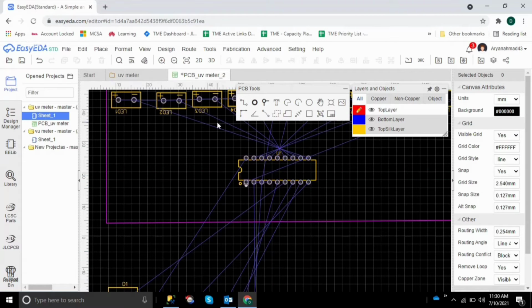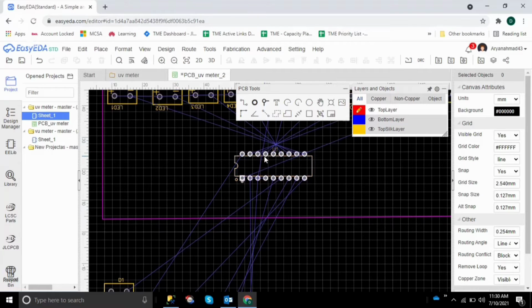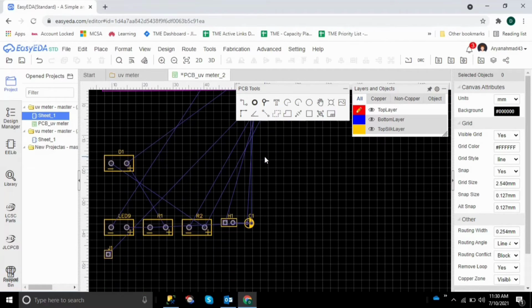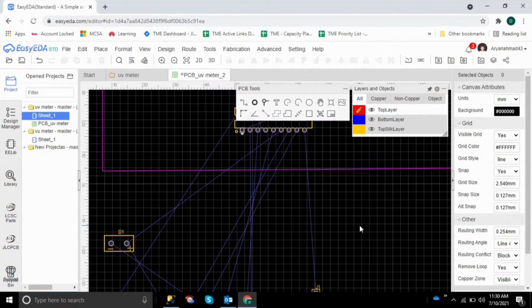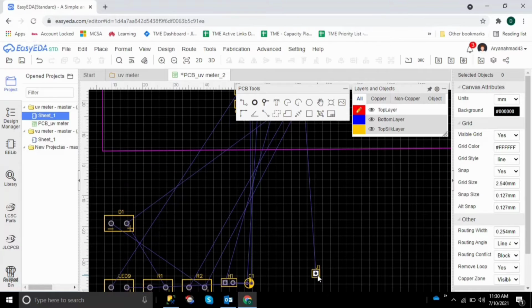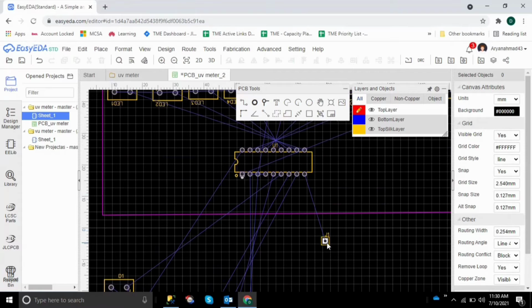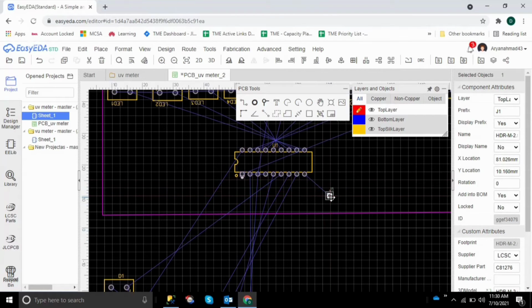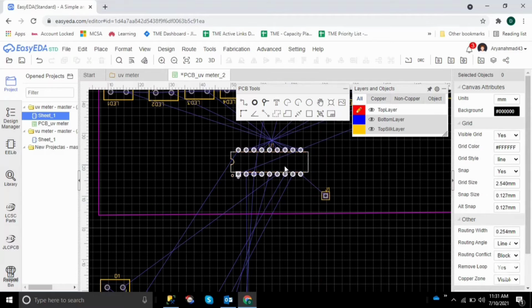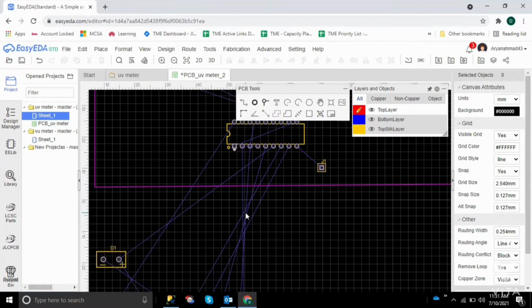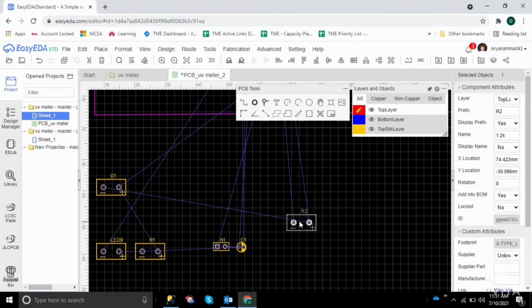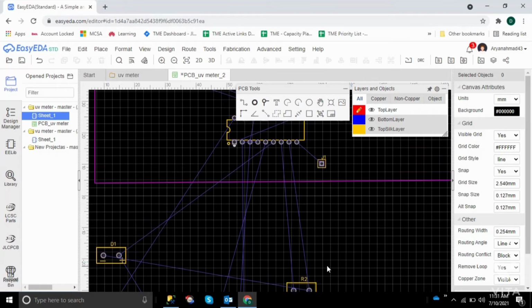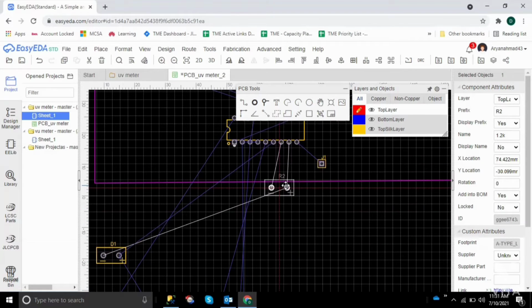Now this time you might see there are twice as many jumpers, so we need to open them one by one. Now with this jumper, which is just an open pin I am using here, place it right there, and then we can see this pin wire goes somewhere down to this resistor. Now with this resistor to the top layer, right there,